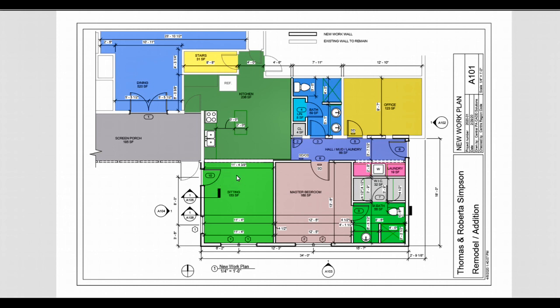So I use those schedules in a lot of different ways, and the first part of it is having the numbers and the designation on the floor plan. The other thing that's important to note is you can see the swings of the doors. So a lot of people will show what the swing of the door is on the schedule. I like to just have that negated or not include that on the schedule and let the contractors look at the floor plan itself to see how they're going to swing.